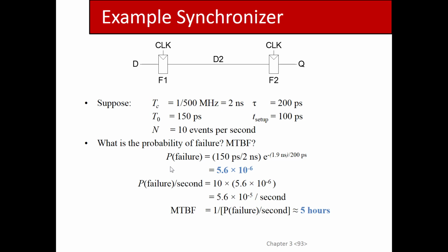If you have to start taking logic out because you're violating timing constraints, then you may have to add more cycles, which will cause you to do more cycles per instruction, right? It'll cause the performance to lower, right? So everyone wants to put as much work into one cycle as they can. In the case of a synchronizer, that's when you can't control it. That's only for external stimuli, stuff coming from outside the chip, like an input device or something like that. So in that case, the best you can do is put a synchronizer in and hope that we can get a clean signal from it.